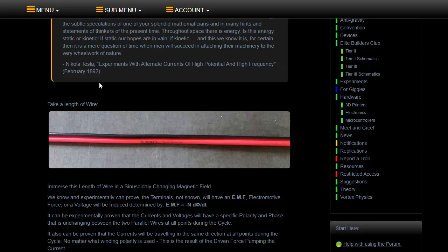So say for example if we had a primary coil that was out over here, off page, not seen, and the primary coil had a magnetic field, which essentially is a current that's changing in time, then the current that's changing in time would induce a voltage on this coil, and then the voltage would allow for a current that would travel in one direction. The current would never change. At one stage I will show a small picture of a coil in the video. It's a long video, I've got to apologise, but we'll show a picture of the coil, or at least this piece of wire, to remind you again of what we're trying to think about here.